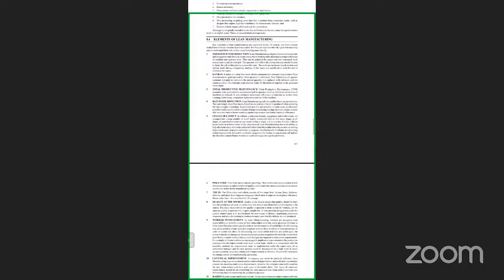Total productive maintenance. Here TPM, that is total productive maintenance, promotes basic preventive maintenance jobs to the operator himself, so the breakdown time of the machine is reduced. It also enhances the operational efficiency of the machine as workers do cleaning, lubricating, inspection and tightening activities on their machine.